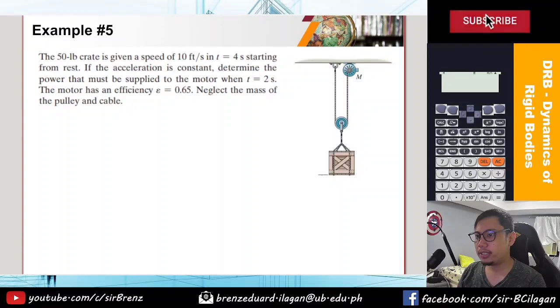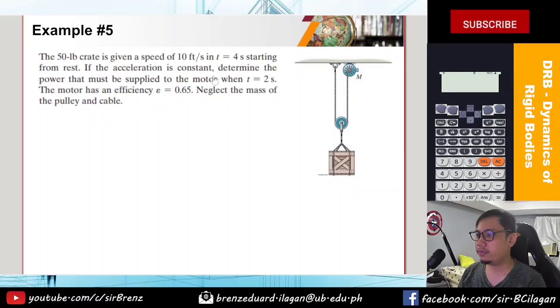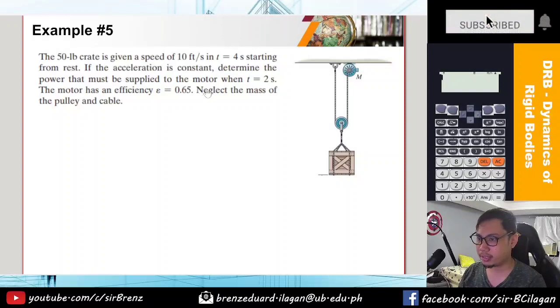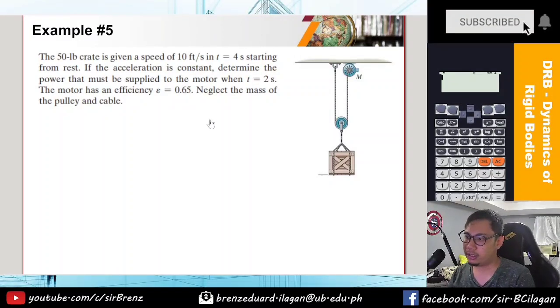Okay, so for our second problem regarding the topic of power and efficiency, we have here a 50-pound crate which is given a speed of 10 feet per second in 4 seconds starting from rest. If the acceleration is constant, determine the power that must be supplied to the motor when the time is equal to 2 seconds. The motor has an efficiency of 0.65. Neglect the mass of the pulley and the cable.